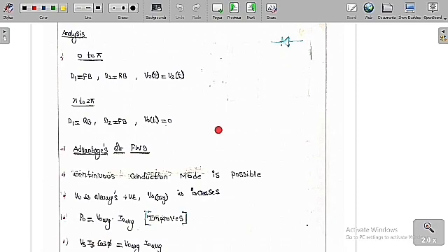So therefore now here the source current is equal to 0 again, because the current is only flowing through the freewheeling diode. So now the source current is equal to 0 in this case, whereas in the previous case the source current is equal to the load current, but here now the source current is going to become 0.